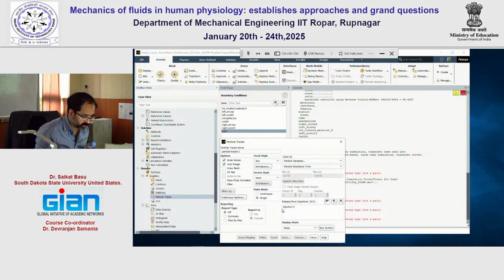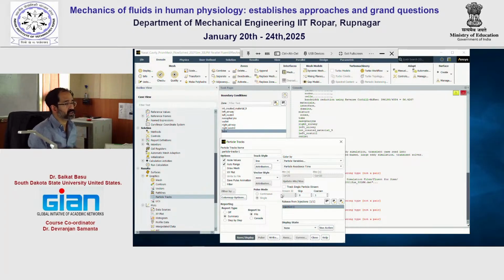Here is where we are going to do the particle tracking. I'm going to generate a summary file, which is called the DPM file, for this tracking. So go to summary and file, and this injection 0 is where we had the cone injection saved. We had missed one thing. Can you guys think a little bit and tell me what we have missed?